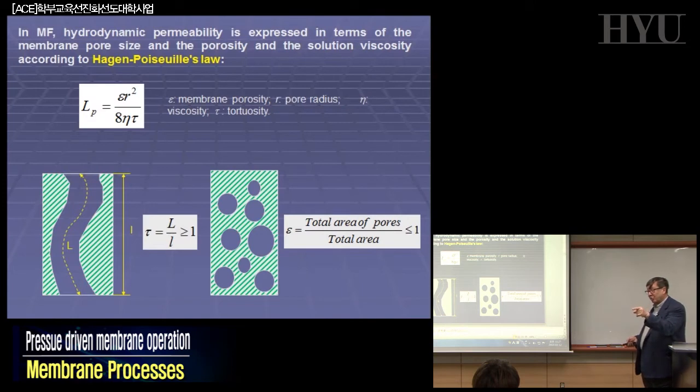When you are in reverse osmosis, these problems don't exist, because all the surface is available to the solubilization and diffusion. And when you're talking about microfiltration, part of the pores are open, and that's the one we are using. Part of the surface is not porous, and this is not useful for the microfiltration. So we have to define this membrane porosity, which is basically surface membrane porosity. Not only the overall porosity that you can measure, but just the surface membrane porosity.